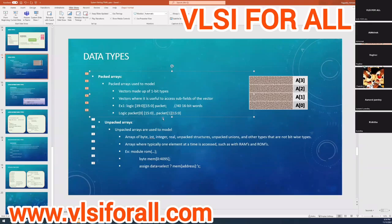So in terms of accessing, it's similar to an unpacked array. But it's only similar in terms of the memory alignment and allocation, and features like slice access. You can access here only 5 down. You can say I want to access only 5 down to 1. You can do that in the case of a packed array. You cannot do that in the case of an unpacked array.